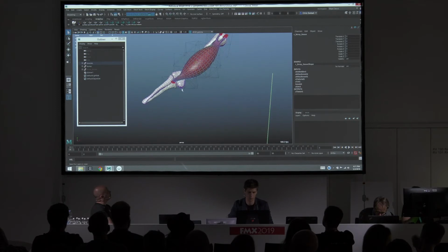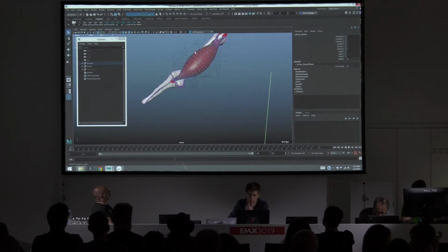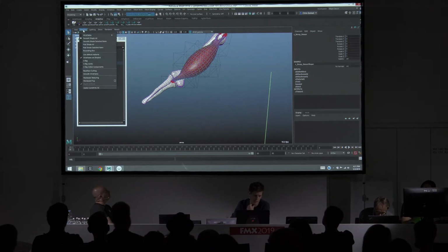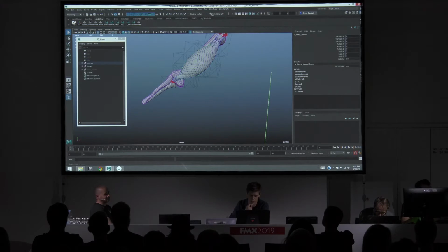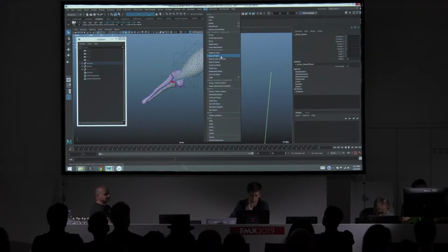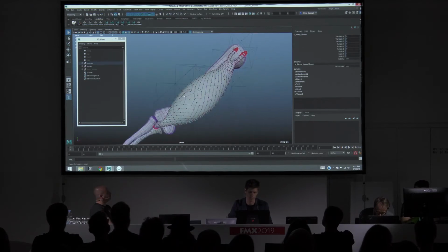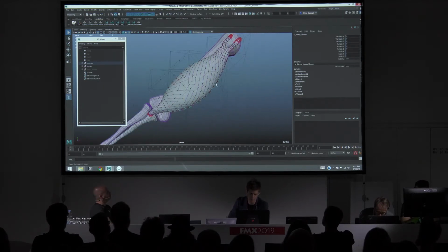So what I'll do next is add a muscle fiber to this. As I'm sure you guys know, muscles are packed with fibers that get excited and allow you to do work. We have that represented in Ziva as well. So I'll change the material now so we can see it a bit easier, and then I'll make a fiber here. You can see that Ziva's tried to guess at the fiber field direction. It usually does a pretty good job.